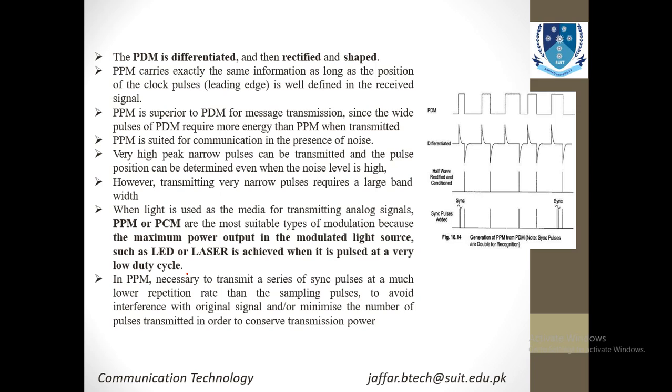The pulse duration modulation is differentiated and then rectified and then shaped. PPM carries the same information as long as the position of the clock pulses is well defined in the received signal. PPM is superior to PDM for message transmission, while pulses of PDM require more energy than PPM when transmitted. So as I have discussed, if the duration of the pulse is enhanced, your energy is going to be enhanced. If you want to control the energy or the power, you have to use PPM.